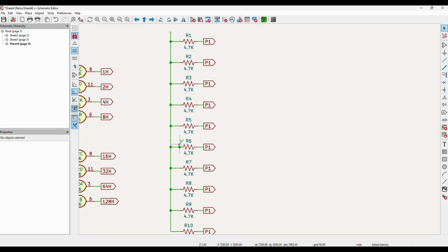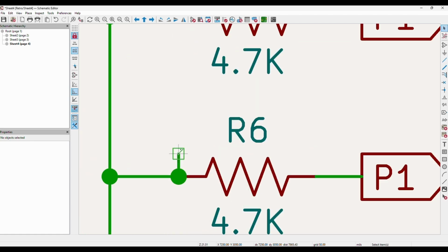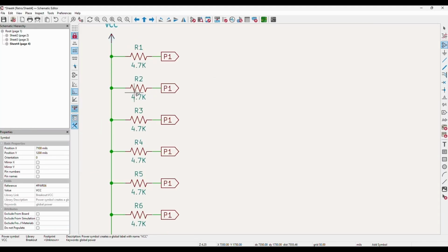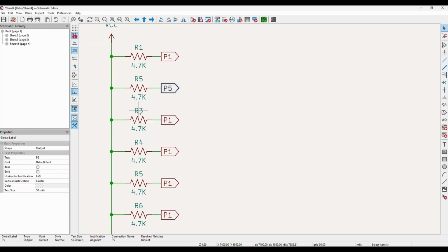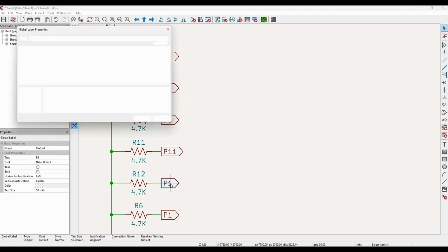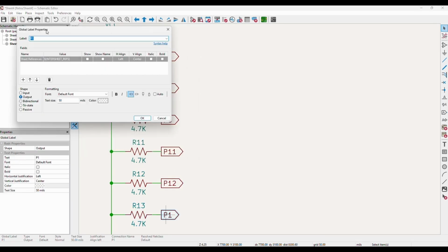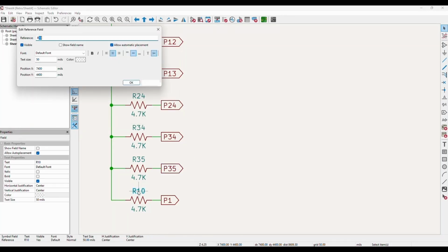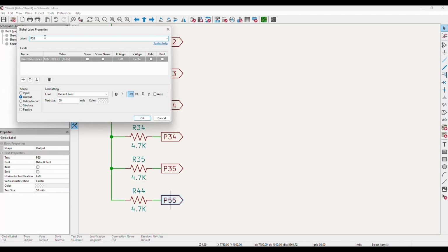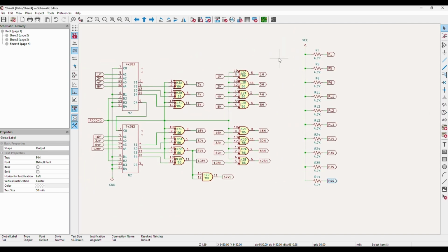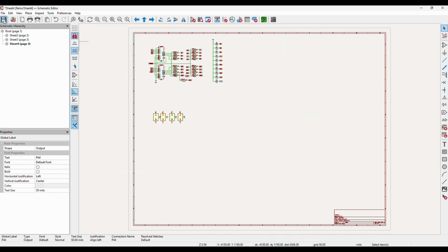For standard TTL, you can't tie inputs to VCC because it saturates the bipolar base collector junction and drives up the current. Low-powered Schottky inputs have a greater than 7 volt breakdown voltage, so we could tie them directly to VCC, but we'll honor the original approach. We'll use 4.7K resistors instead of 1K, however. These are all static lines, so we can take it easy. For active pull-ups, you can lower the resistance to improve rise time slightly. Looks like a winner.